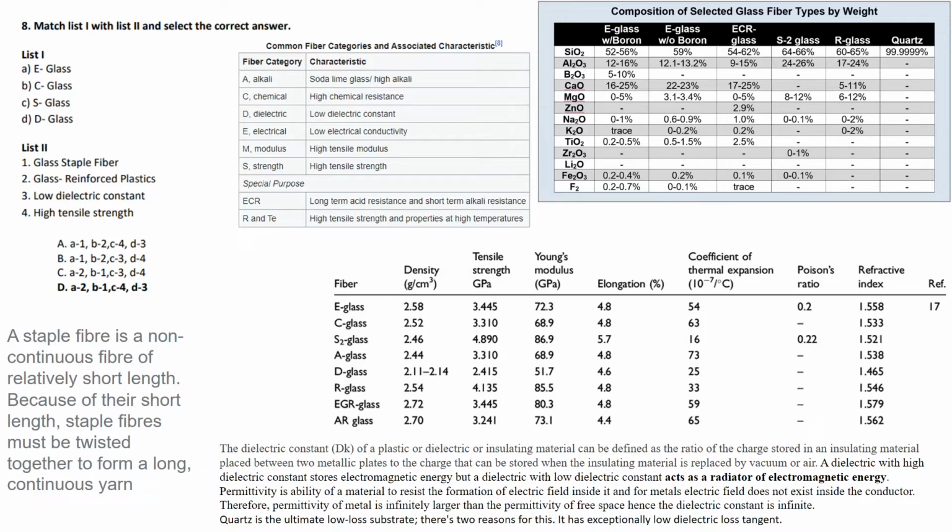E-glass for commercial applications, what you see is its cost and its performance. Fine. So E-glass is used in most of the places. It's the most common glass fiber which you'll find in composites made out of glass fiber, like bonnets of cars and all these daily use applications.